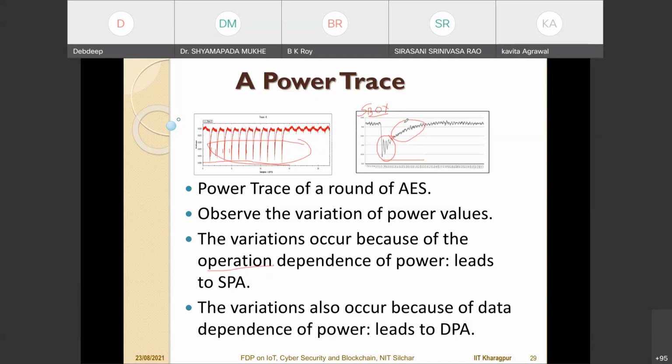But for AES and AES kind of ciphers, it is not so straightforward, and therefore you need to resort to a technique which is called differential power attack, which tries to exploit the fact that the power consumption depends upon the underlying data on which the operations are based. This is an even more powerful form of attack, and we will take a look.